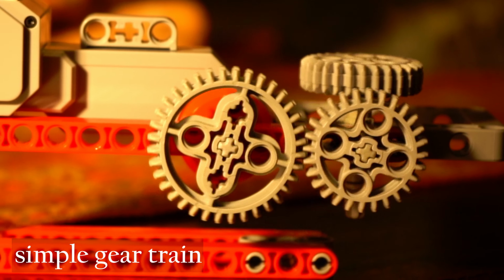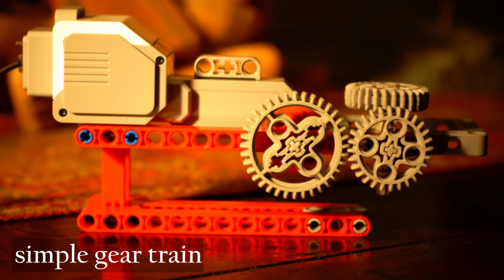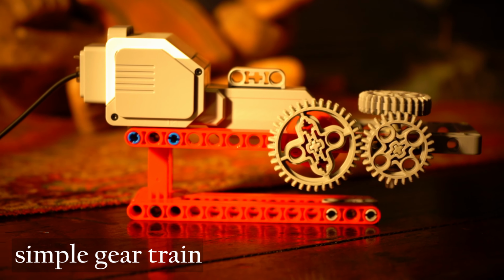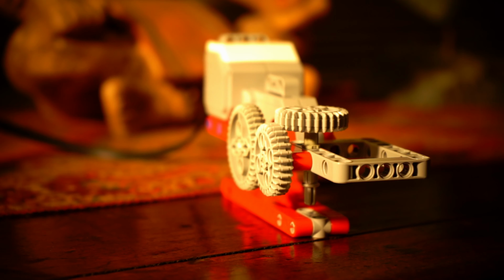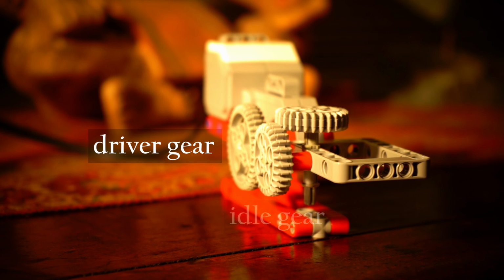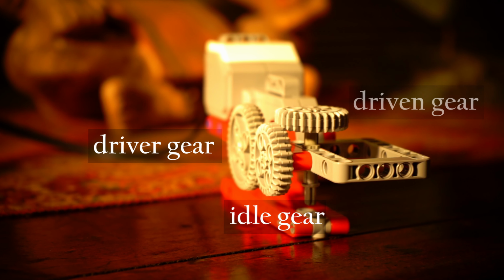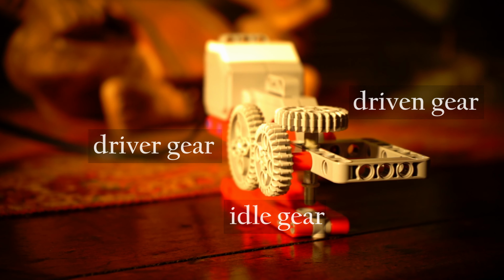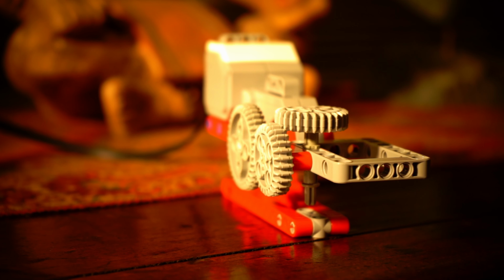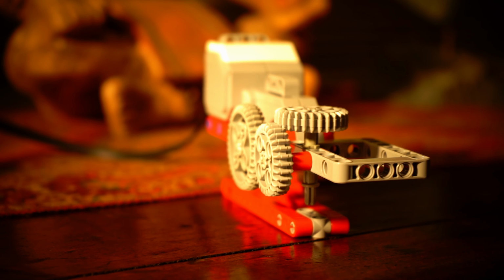However, simple gear trains are not always in line and can be constructed at right angles with bevel gears, double bevel gears, worm gears, or knob wheels. Here, a 36-tooth double bevel gear, the driver, turns a 28-tooth double bevel, the idle gear, which turns a second 28-tooth double bevel, the driven gear, at a 90-degree angle. This video focuses only on gear trains in which all gears are inline, that is, occurring in the same plane and having parallel axles.